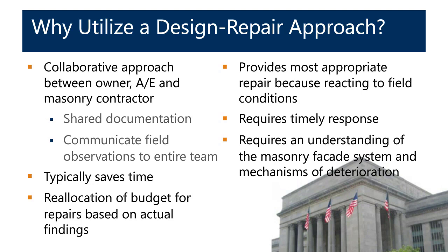It typically saves time. It allows for the reallocation of budget for repairs based on the actual findings when we get up close to the facade and understand what's actually going on. It can provide for appropriate repairs because we're reacting to those field conditions and really understanding the source of deterioration and distress. But it requires a timely response from everyone on the team. And it also requires an understanding of the masonry facade system and the mechanisms of deterioration.